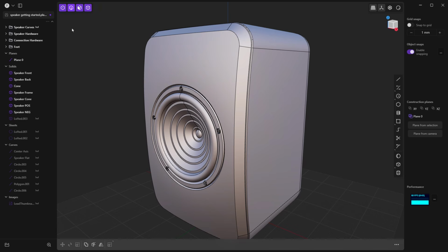Also note that you can hit the Tab key to go back to all selection as long as you're not currently doing something. And what I mean by that is if you're, let's say, drawing a line, then hitting Tab is going to jump to the dimension for the line rather than changing your selection filter. So I would just get comfortable with using 1, 2, 3, 4, and 5 across the top of the keyboard, and that's going to help you quickly go back and forth between your selection filters. In most cases, you're likely going to jump between all and maybe the edge selection.